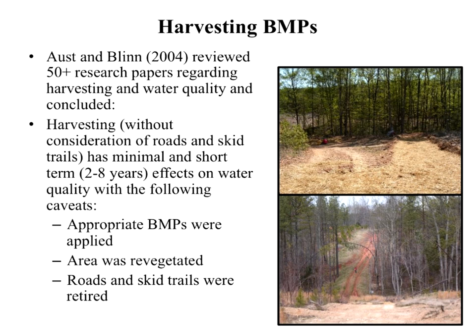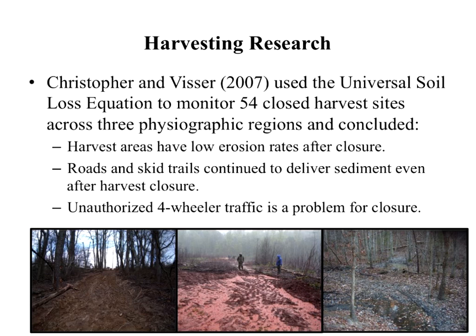If you take a look at the lower slide, we see that the road is about a 17% slope coming down on one side and about a 19% slope on the other. The water control structures are failing. Sediment is being delivered to this particular stream. The road itself is rutting out. Again, clearly one where we need to come back in and do something pretty drastic. Okay, but again, that's the caveat. We can have the roads and the skid trails and the stream crossings, but we have to be careful with them. They can make a mess in a hurry.